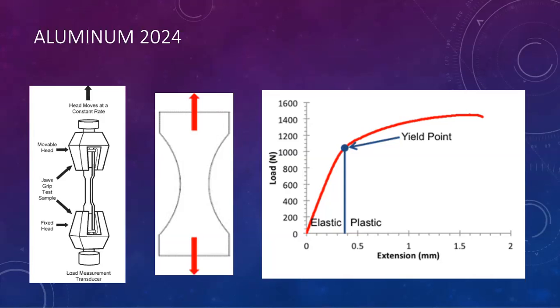It's permanently changed. One of the important things is that this does not always mean that there's a crack or micro fractures happening. It could just be plastic deformation that will lead to that eventually. So all those other tests we talked about cannot detect before there's a crack. We believe that we could.